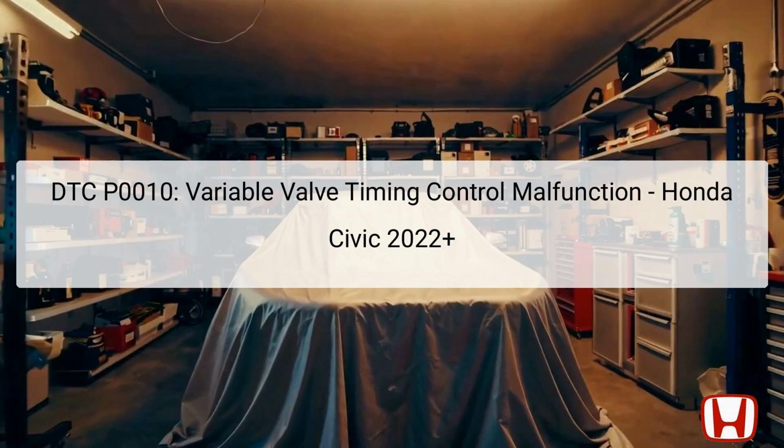When the powertrain control module, PCM, detects a discrepancy between the commanded and the actual current flowing through the solenoid, it records this anomaly and triggers DTC P0010. It's essential to address this issue, as a malfunctioning VTC solenoid can lead to poor engine performance, increased emissions, or potential engine damage. The proper functioning of this component is vital for maintaining optimal engine operation across various speed and